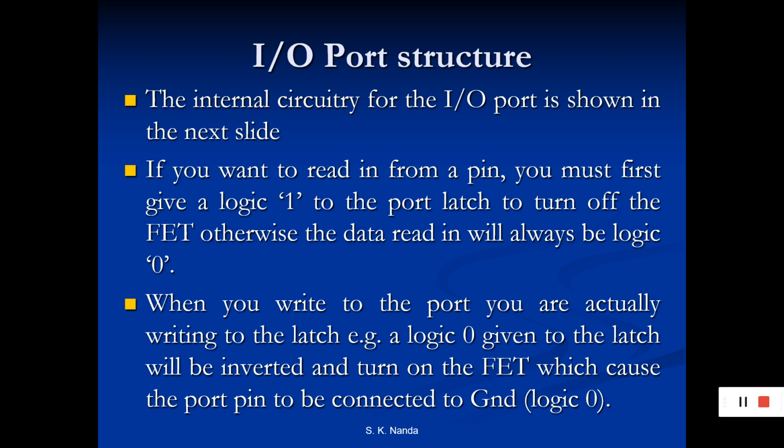If you want to read in from a pin, you must first give a logic 1 to port latch to turn off the FET, that is transistor. Otherwise, the data read in will be logic 0. When you write to the port, you are actually writing to the latch. For example, a logic 0 given to latch will be inverted and turn on the transistor, that is FET, which causes the port pin to be connected to ground, that is logic 0.